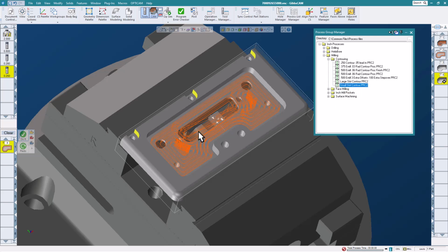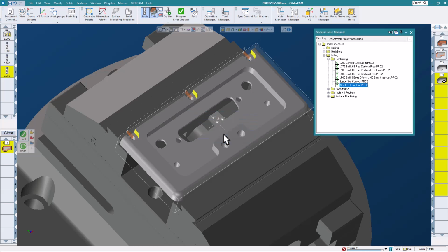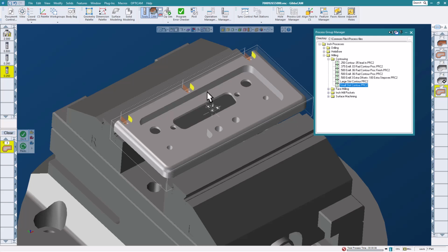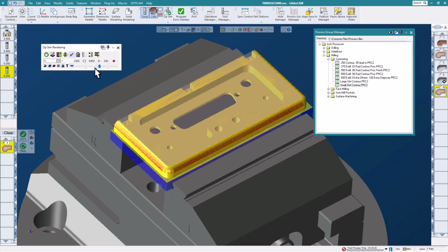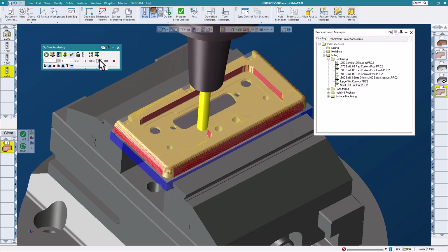So I have something called a small slot contour, and we'll say do that. And again, I use the slice body to give me analytic tool paths. So, you know, it's a bit cleaner tool path, or I shouldn't say that it's a cleaner toolpath. The G code is a bit less because we're using lines and arcs. Okay, so far so good. So far, if I go back to the beginning here, we've faced off the part and it went pretty fast. So sorry, milled it to the pockets and now did the slots. And so far everything looks pretty good.